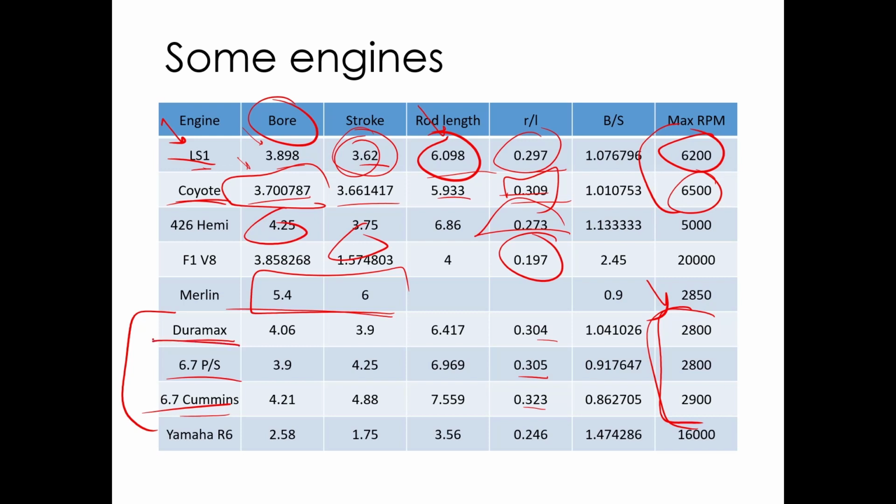So I have a truck that's got the Duramax in it, and when you're driving forward, it shifts somewhere in the low to mid 2,000 RPM. It really stops making power after 2,800 RPM. That's when the pumping loss is. There's a lot of flow restriction, even though it's got a turbocharger. It's not sized to breathe in a lot more air than what the 400 horsepower or so it's rated at.